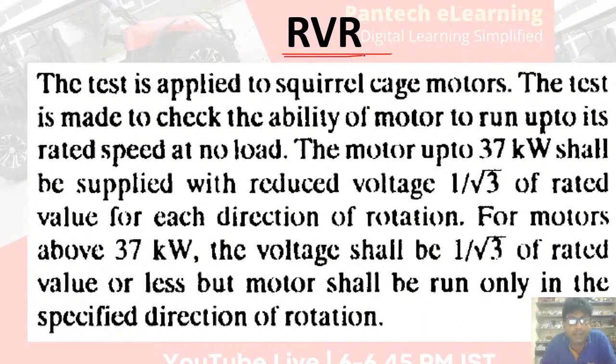Reduced voltage running up test. This test is done up to the motor rating of 37 kilowatt. Above 37 kilowatt, these tests are not done.